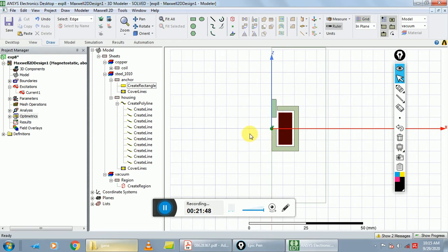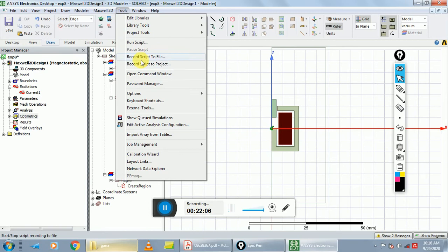After that next step is setting DSO analysis. For DSO analysis, here we activate a DSO solver. Basically DSO is a distributed solver option. For distributed solver option, go to tools and option, click on HPC and analysis option.